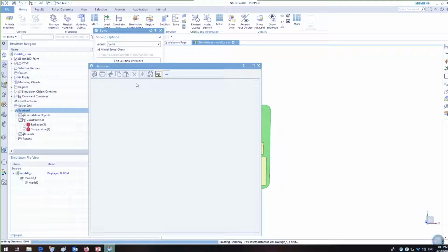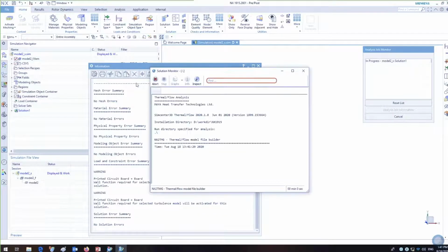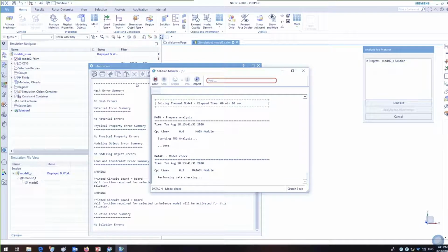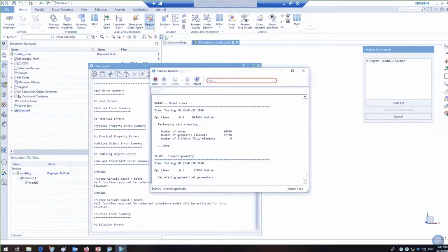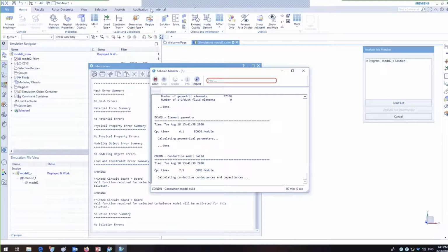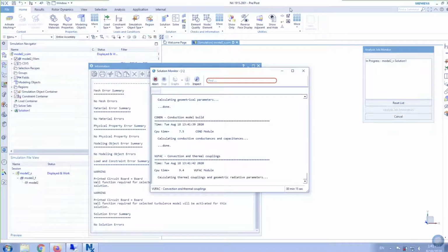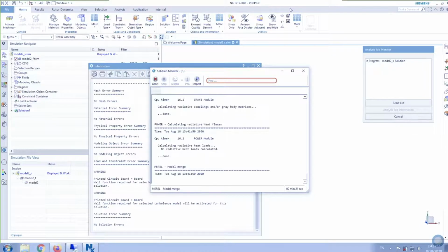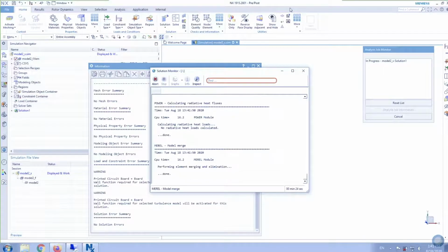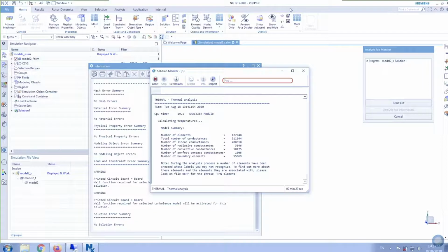Like I mentioned before, the board is a 2D mesh in the UI, but in the solver we are actually getting separate meshes for every layer, and for every layer we'll have temperature results. So we'll be able to probe the gradient across the board on every layer, and we'll get the temperatures for the junctions and the cases of the components.